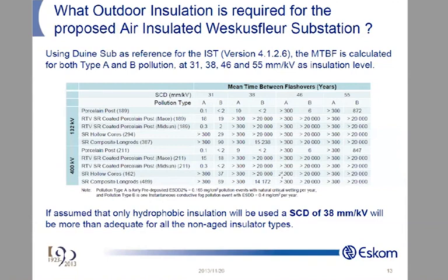If it's conductive, it's tracking. If it's not conductive, it's erosion. Normally silicon has problems because of its composition and material structure; normally the silicons erode. But I didn't diversify too much, not answering your question.